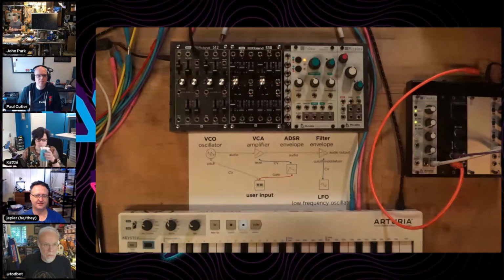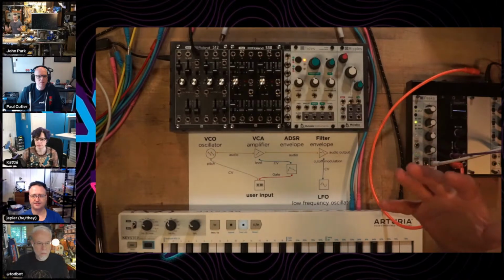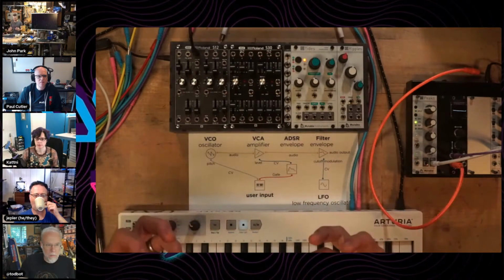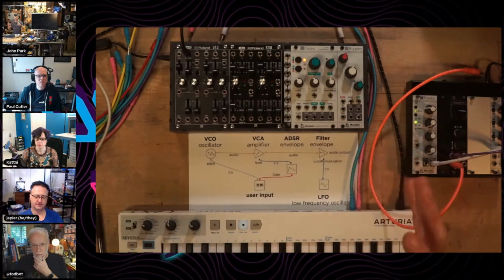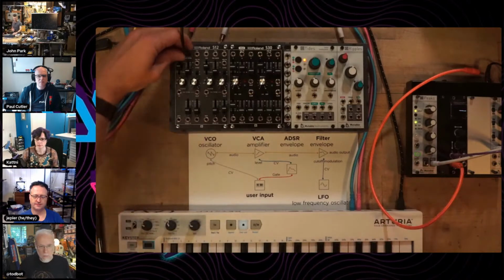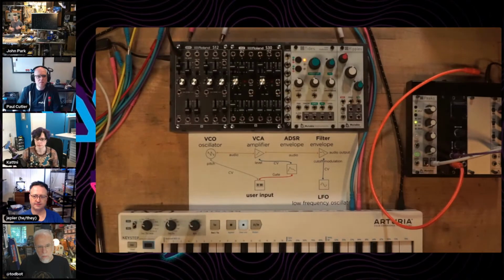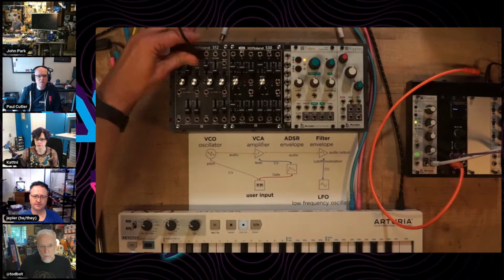That's good. Okay. So that is a fixed pitch of what's called a sawtooth wave. The shape that you see right here is the shape of that wave. So it's got a lot of harmonics to it. If I go to a triangle wave, it sounds a little smoother, doesn't have all that rich harmonic content. It's a little more of the fundamental note that we're hearing. If I do a type of square wave that's called pulse width modulated, it's got lots of cool harmonics and it has the ability to emphasize certain harmonics over others.